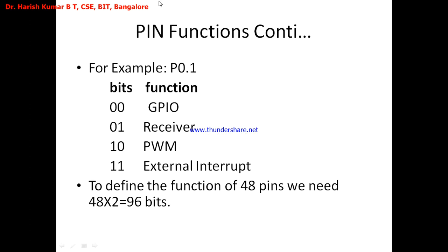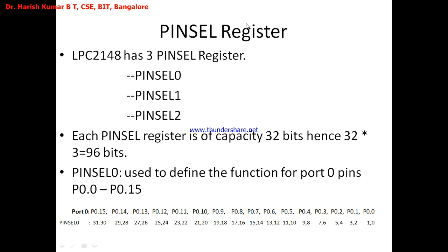Now in order to achieve this, LPC2148 has something called PINSEL registers, meaning pin select registers. LPC2148 has 3 PINSEL registers: PINSEL 0, PINSEL 1, PINSEL 2. Pin select register 0, pin select register 1, pin select register 2. Each PINSEL register has a capacity of 32 bits, hence 32 into 3. I have 3 such registers, and the capacity of each register is 32 bits.